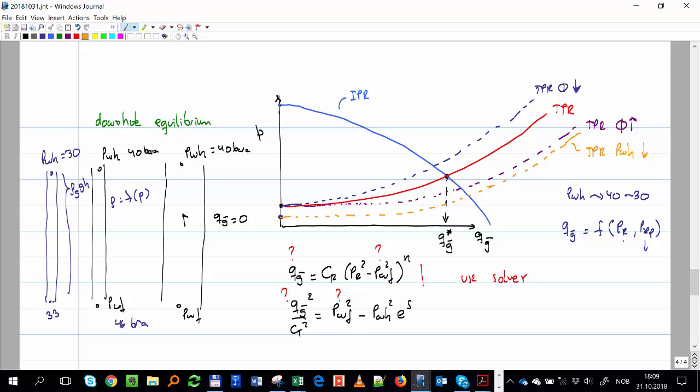you see it has a similar shape to the red curve. Let's make it solid so that you can see it better. It has a similar shape, but the origin is different, because the static pressure is different, and also you're getting more rate because the pressure is lower, so you're getting more rate than with the high wellhead pressure case. Is that clear? You can explain that one again.